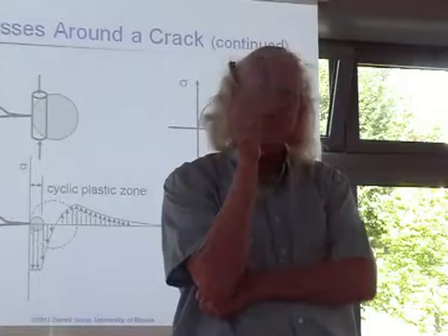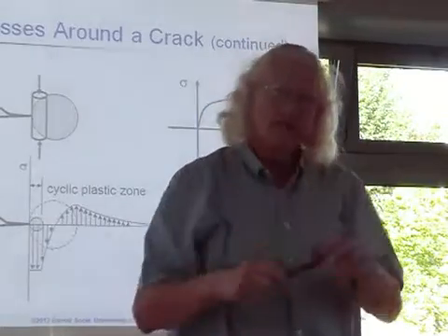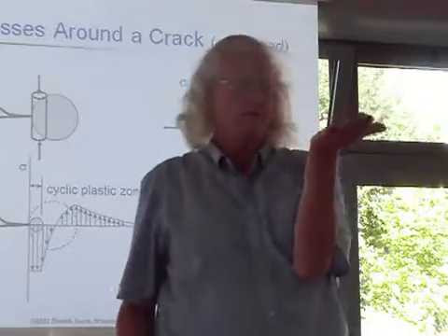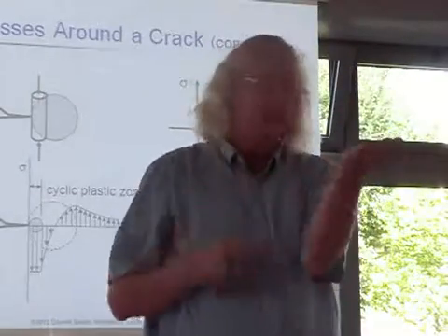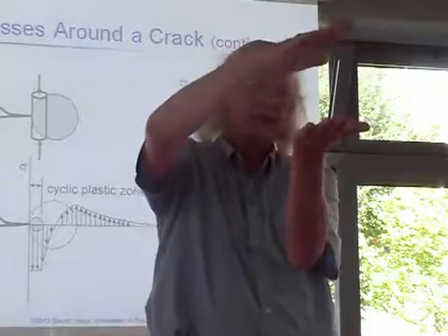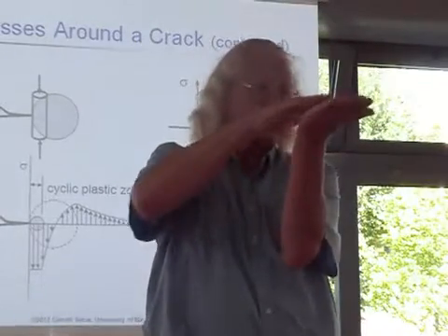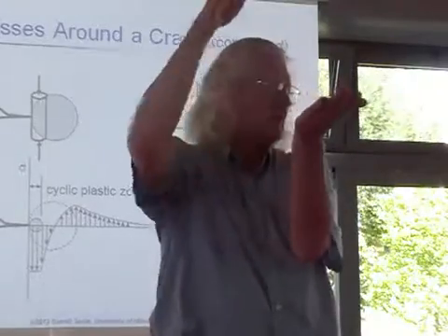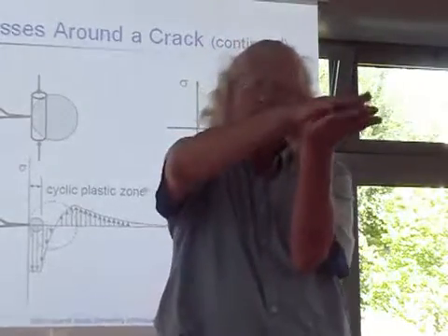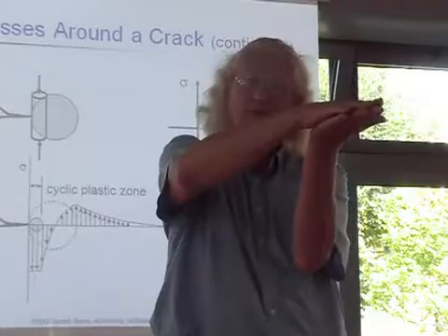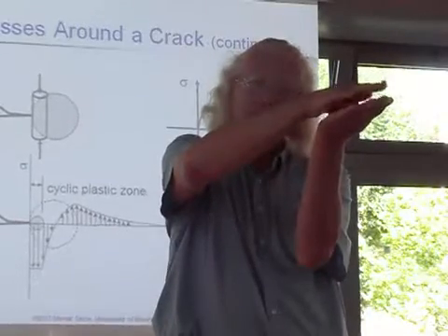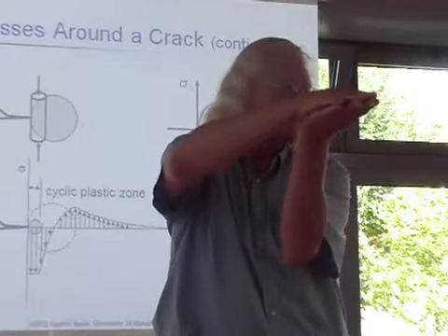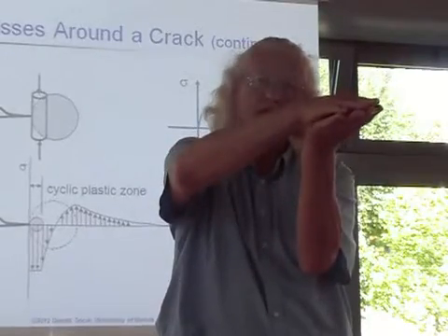That's the difference, right? So if you view what happens at the crack tip, let's do a little thought experiment. I have one plate here, and I take a second plate and put it on top. So I guess you could say the interface is like a crack. Sure, mechanics-wise, it's exactly like a crack. I can press on this forever and nothing happens. I can press on this forever, nothing happens. The only way I can fail these two plates is to put the smallest amount of tension, and then I can open this up.